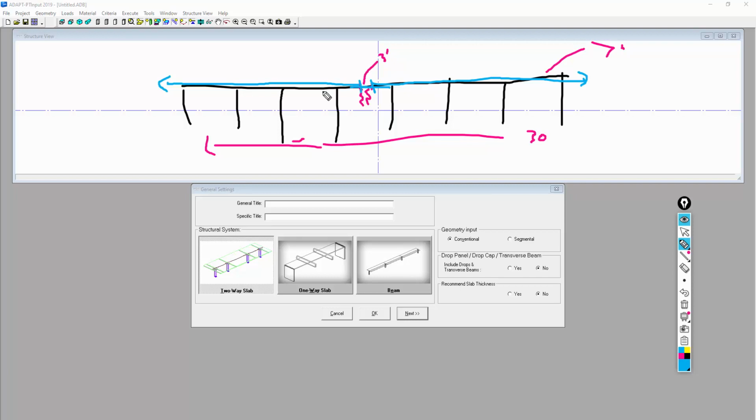You could build multiple models that might be required to capture different stages. For example, if the shoring is not here, and this is a cantilever, let's say left, and a cantilever right, we might have to build 3 models. We might have to look at model 1 on this left side, model 2 on this side. Those are completed in different stages, and then model 3 is the full system again. So we're really looking at model 3, assuming that this is short. And what we're going to focus on is really how to set the tendons up here.